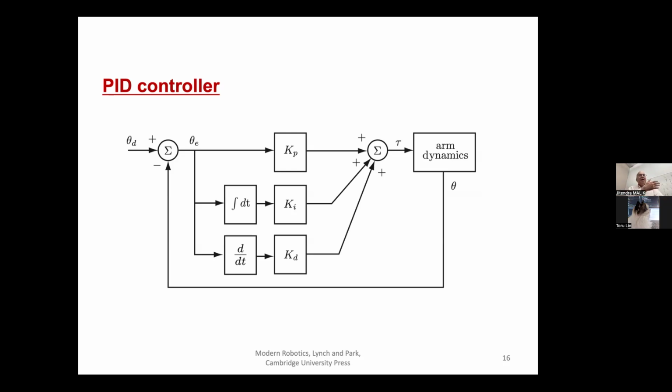And I will tell you how we will deal with it now, because actually in practical robotic systems we still have to deal with these controllers, because the lowest level controllers, the ones which control the motors at the joints, are actually PID controllers. So in fact, the setting of these constraints can be done by a higher level. Your higher level reinforcement learning algorithm can, among its output, produce the right choices of these constraint scale. So that can be the output of your RL